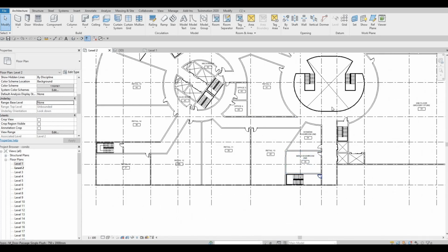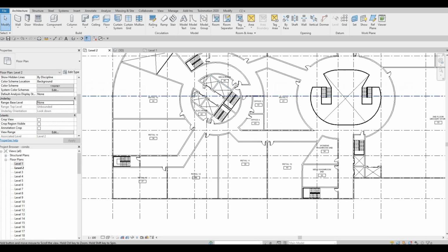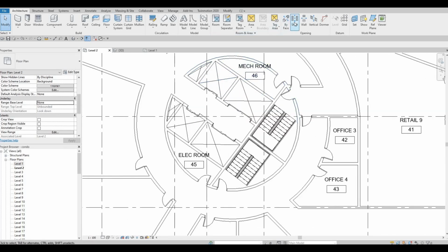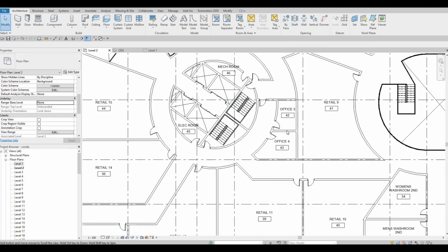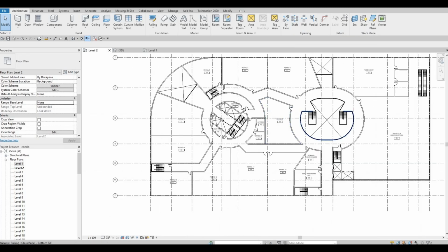This one you could just open, or you could just click the floor again and just create an opening. So that's easy to do. But here it's gonna be a different. It's better to use a shaft instead of opening each and every floor. You can do that when we group a floor. So you could just click on open or create an opening from each floor because everything is grouped. But at least this is the proper way of doing it if you want to do. So I'm gonna show it to you guys.